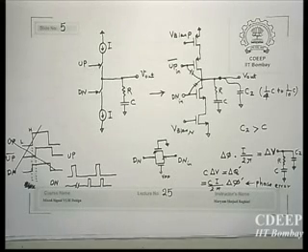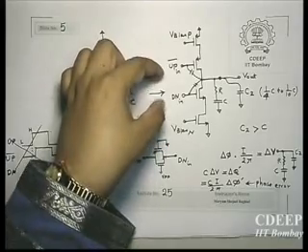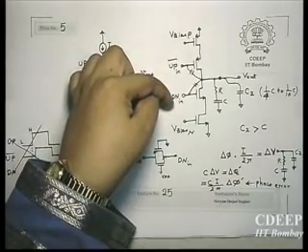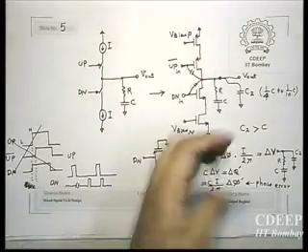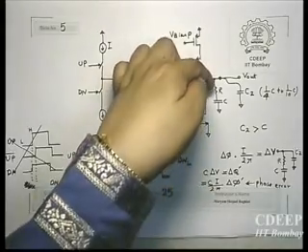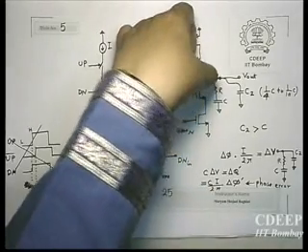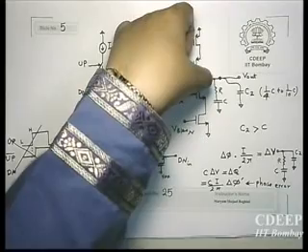Or even, for example, when both of them are equal and both come together, meaning up bar is 0 and down is 1, you expect these two branches to conduct the same current, therefore there won't be any charge accumulation or reduction on C. This is also a steady state.